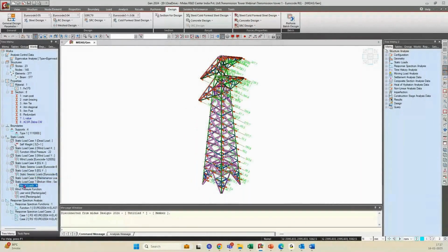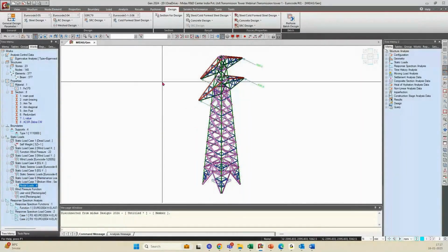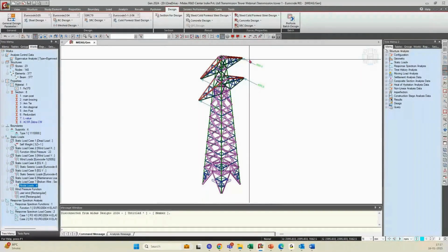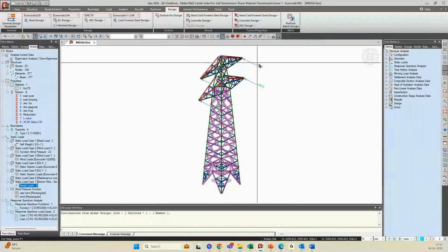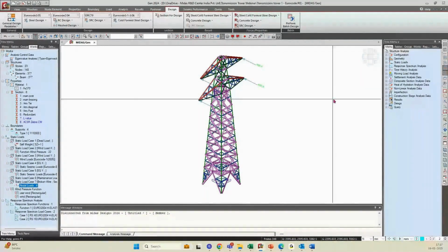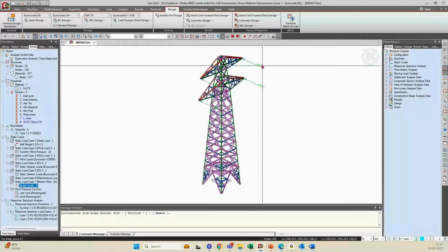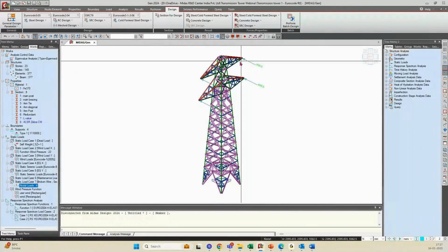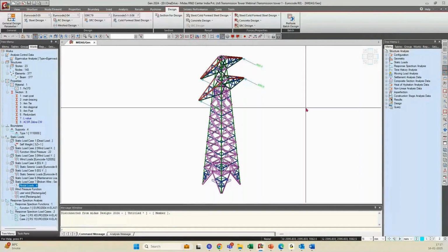and we can also apply the loads due to the cables. Okay, the conductor wire loads can be applied here. If they're exactly straight, we can apply in the perpendicular direction. So if they are in any inclined direction with a certain angle, we can resolve it and apply the forces in two different directions. Okay,